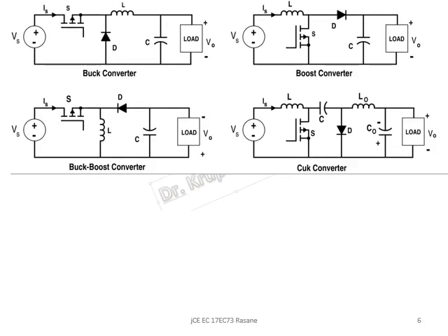So these are the four circuits that we had seen earlier. In the buck converter, we have seen the switch coming in series with the voltage power supply, and here in the boost converter we can see the switch is coming in parallel with the load as well as the source, and we have this inductor in series with the source.